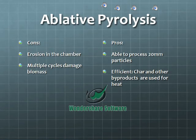There are two main disadvantages to the process. The first is that vapors sometimes will accidentally get recycled through the vortex reactor twice, which overheats the vapors and severely damages them. In addition, the biomass travels into the vortex reactor very quickly and at a perpendicular angle to ensure that each and every particle of biomass undergoes the heat released by the friction of the inner walls. However, this transition from linear to angular momentum causes significant erosion in the vortex reactor. This erosion adds to maintenance costs.